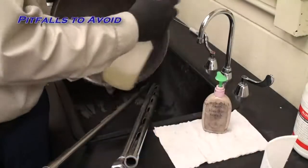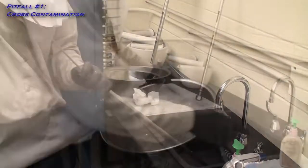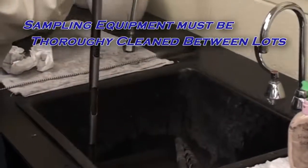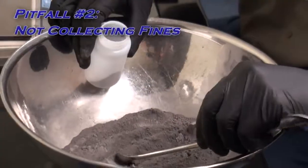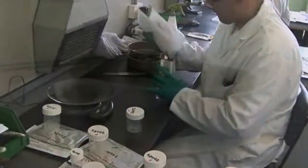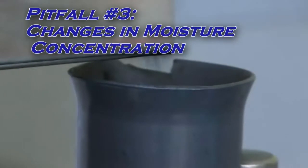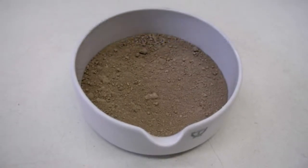There are a number of traps that can produce misleading results that care and handling should avoid. Cross-contamination from one sample to the next could occur if sampling equipment is not cleaned adequately between lots. Care must be taken to collect all of the dust when crushing, grinding, or handling fine materials, as some dusts have different metal concentrations than the bulk. Fine particles may also pick up or lose moisture while passing through sampling equipment. Although they may not appear wet, they may contain enough moisture to affect results, so this should be accounted for.